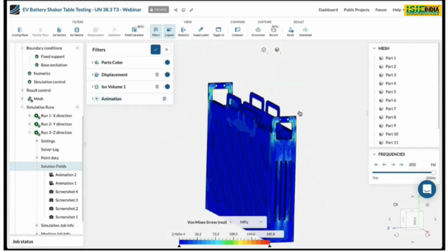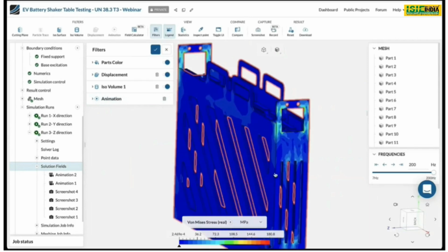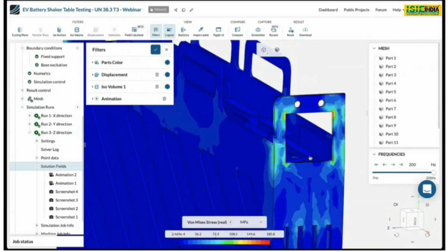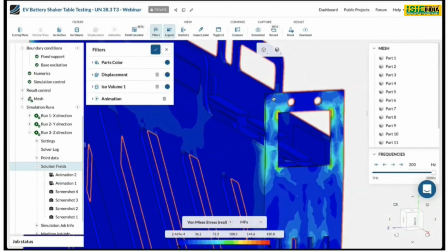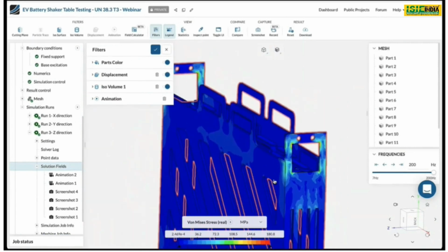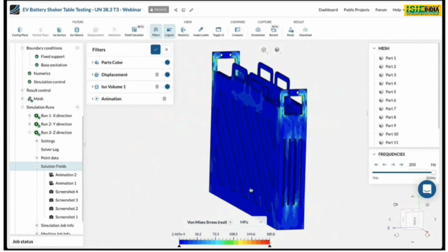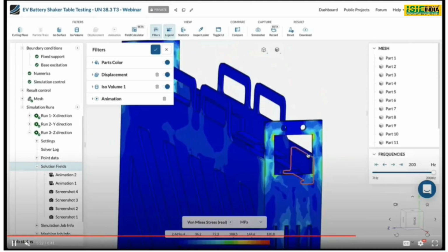So we'll see the stress now after doing the simulation for some time. So here you can see we had fixed 2 points, and now the maximum stress is taken at these points. So here you can see the different types of color is showing it. The stress is increasing as per the fixture is given at the left and right corner side of the casing. So ideally, these types of tools are majorly used to determine the strength of a cell or the casing.